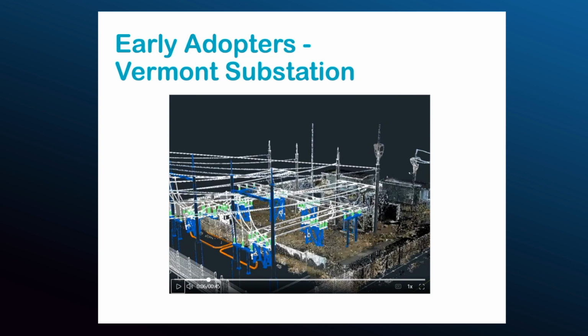So at the moment, it's supplied off a single 66 kV feed that's cut across into those two lines over here on the right. So a key part of our consideration here is trying to build underneath what would be effectively energized conductors. That's always a really big hazard and a big unknown until you hit site and get working. That's generally where you really find out what it's going to be like.